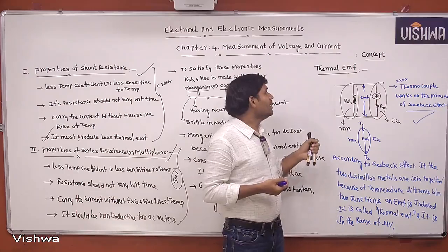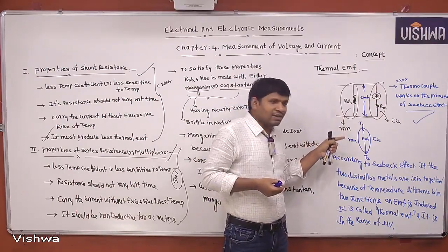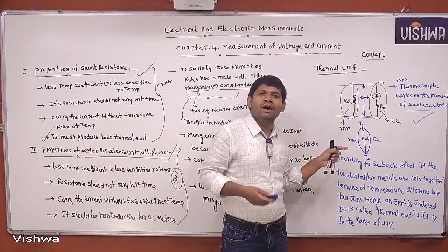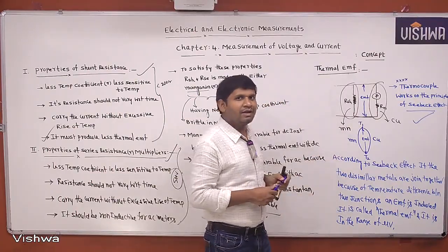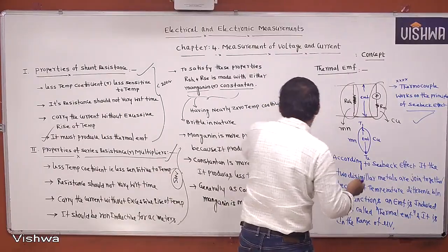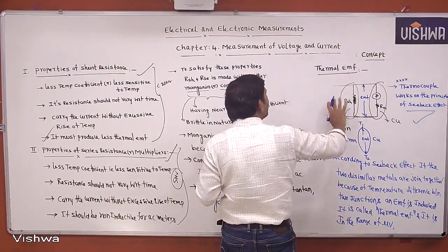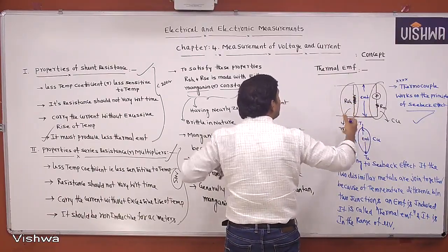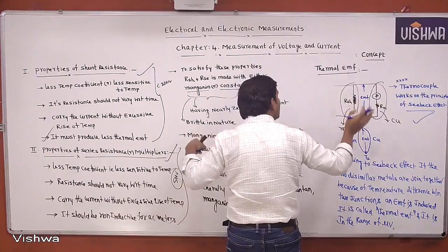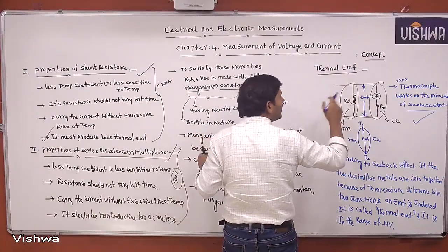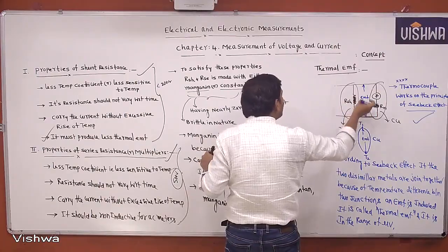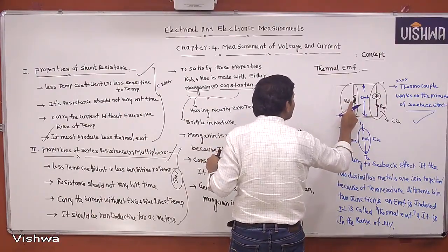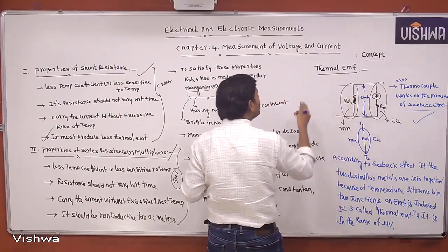That's why if the shunts are made with copper, size and weight of the meter increase and temperature errors also increase. Remember that note also. In order to eliminate thermal EMF, using copper for the shunt is meaningless. Microvolts means it is a negligible effect, no doubt at all, but copper gives more temperature errors.